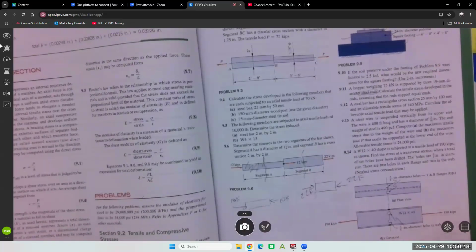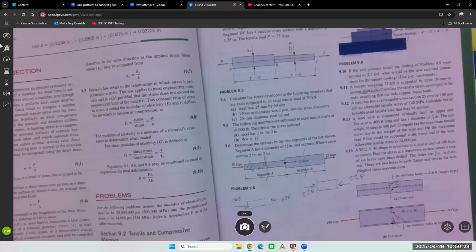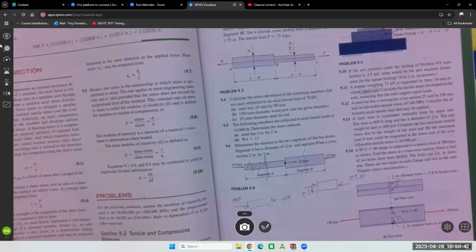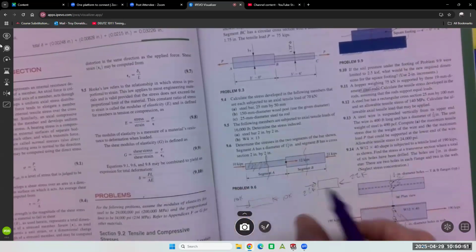So we did a lot of this. Chapter 9, we did a lot of. So I would expect at least a couple problems in class on this kind of thing. Look back over your homework and your notes, organize that thought. Big part of this test is categorizing the problem. Like, oh, this problem is a compressive stress problem, or an inertia problem, or an elongation problem, right? There's our elongation equation, PL over AE on the axis.